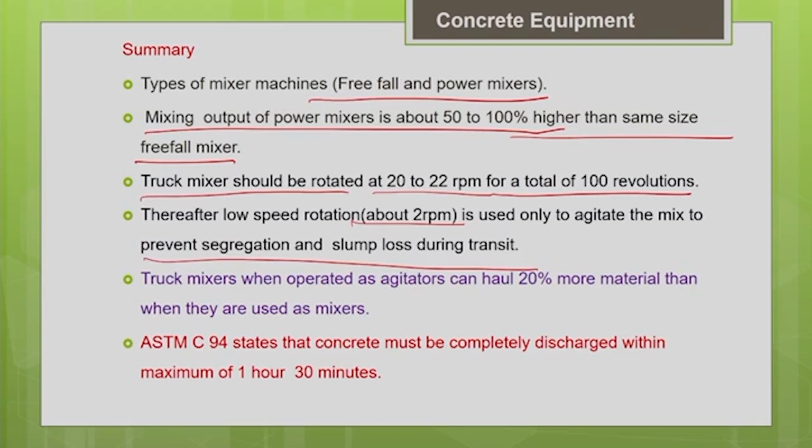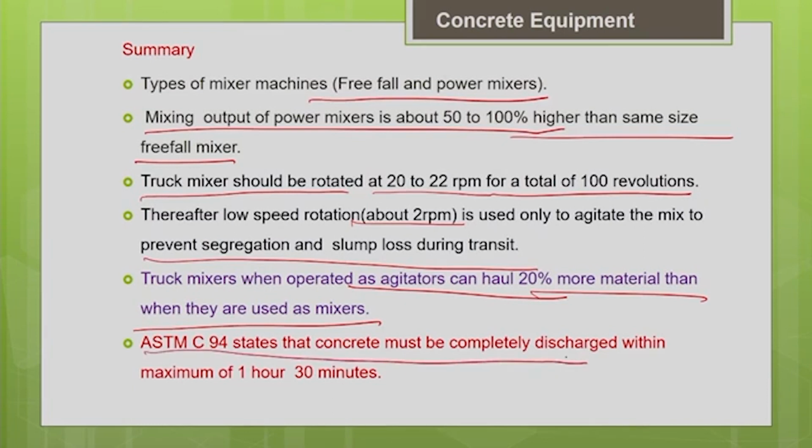Okay. So, if you are going to use your transit mixers as agitators, it can handle 20% more material than when used as the truck mixer. Okay. And we should always keep in mind that the time is very critical in the concrete making process. So, ASTM states that concrete must be completely discharged within maximum of 1 hour 30 minutes. Okay. From the moment you add the water for preparing the concrete to the moment you discharge the concrete, the permissible time interval is only 1 hour 30 minutes. That is a maximum limit allowed.